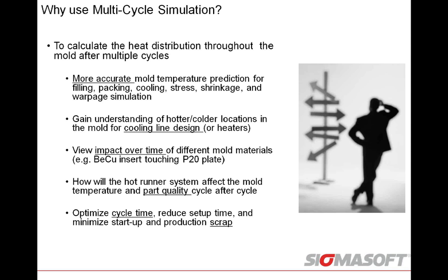And then if we look at our hot runner system, putting a great amount of heat load, if you have a hot runner manifold and hot runner drops within your mold, let's look at how that is affecting your mold temperature as well, but also the part quality cycle after cycle. As that polymer is sitting in that runner system, you have a residence time. How long is that polymer sitting in there, and how is that heat load after 1, 2, 3, 4, 5 cycles again impacting the heat distribution, the heat flow through that mold.